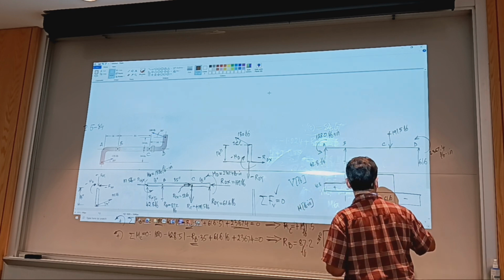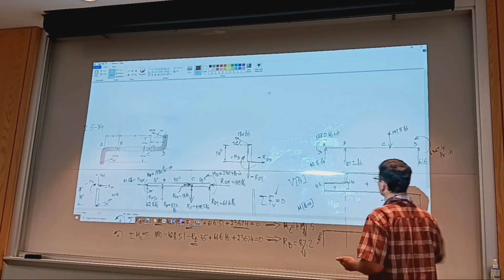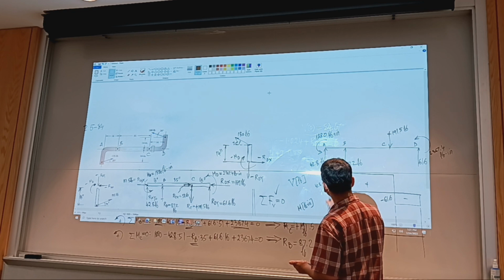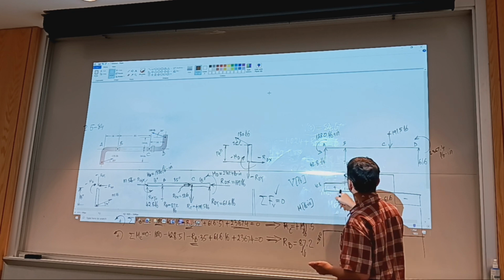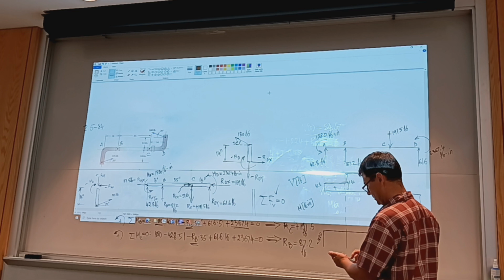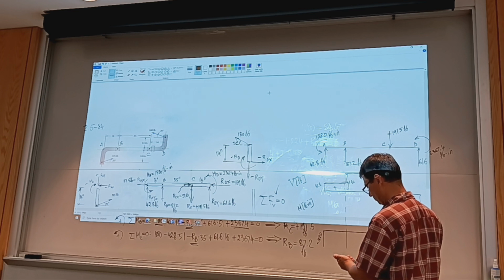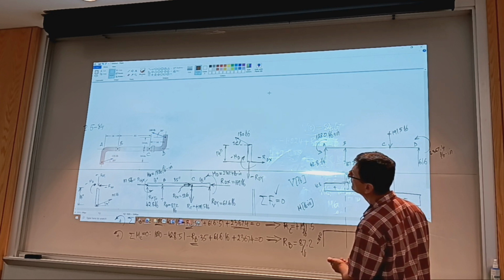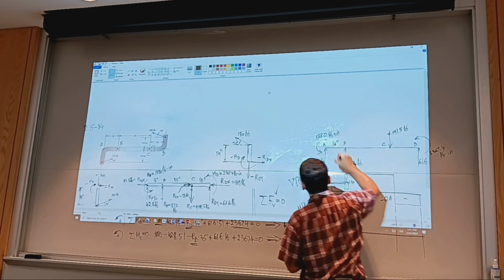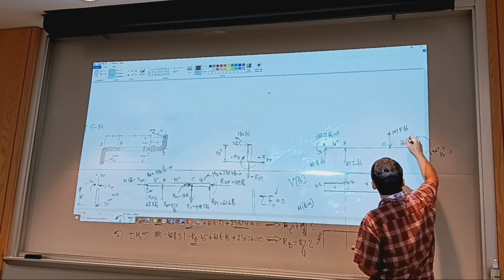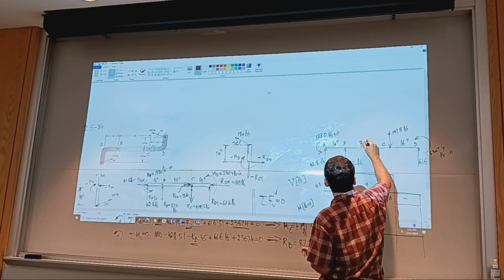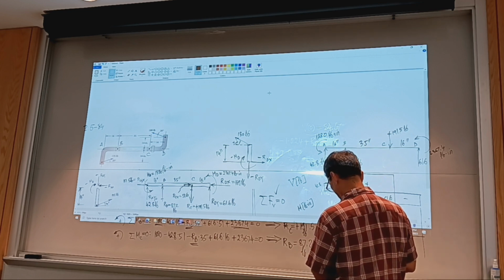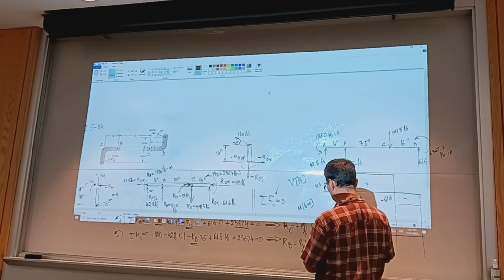And let's see what it gets us when you get to point B. So negative 1880 plus the area under the shear diagram. So I have negative 1,880 plus 42.8 multiplied by the 16 inches. Okay, so it's still negative.